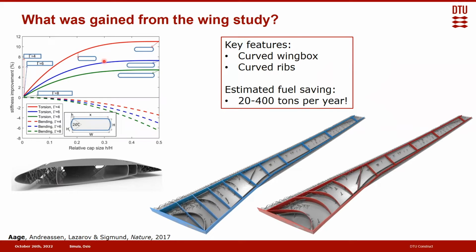Might not sound like much, but when you talk of aircraft design, if you go for the conventional separation, you have the fluid in the actual wing, and you don't want to have bathtubs you're flying around with. That's going to be nasty for stability and not so good for safety. If you did them curved instead with the same mass, you could get another few percent in weight reduction without going for this completely maniac crazy design, which, by the way, the main comment we got from both Airbus and Boeing was, this will hurt when struck by lightning. So they all imposed a lightning constraint on our designs.